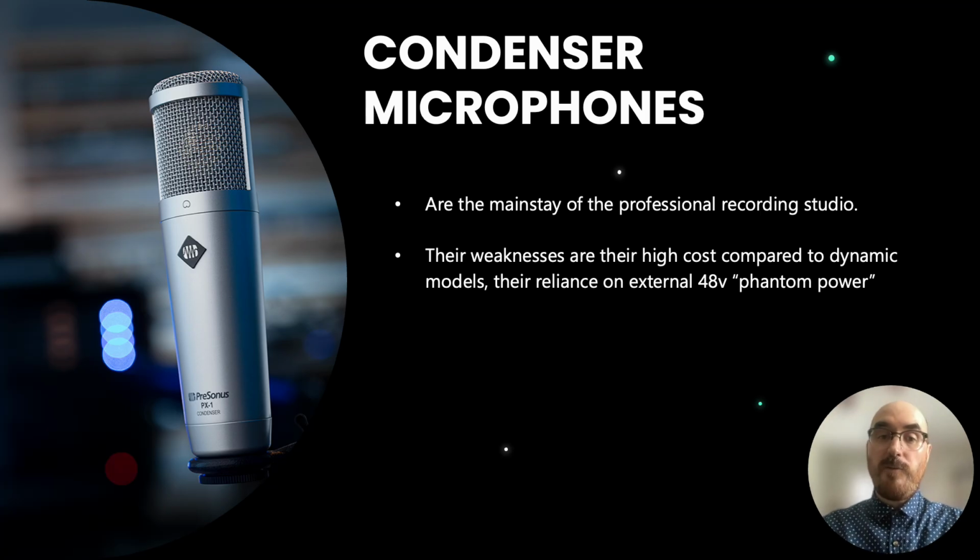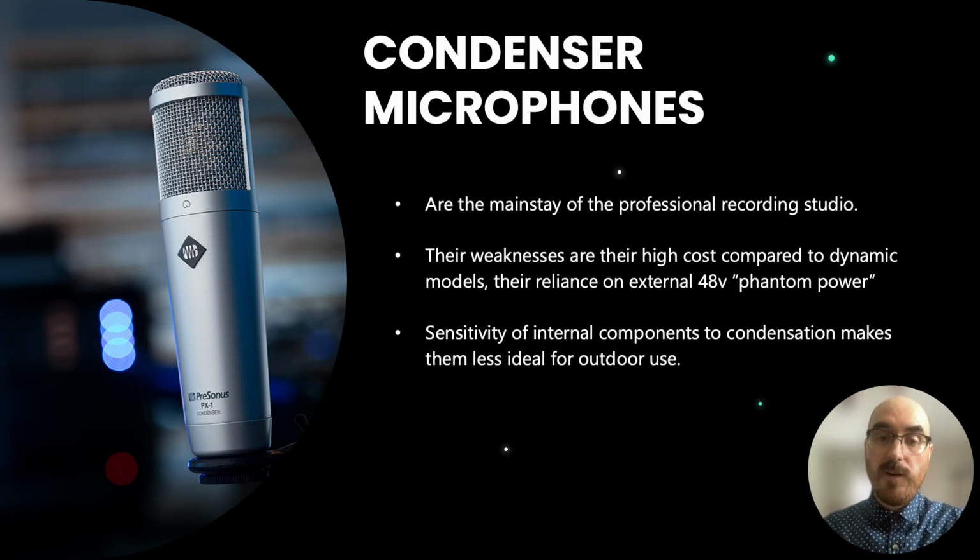So these microphones have circuitry that needs a little bit of power. So you're going to be using your microphone cable not just to pass signal from the mic to the audio interface, but you're also going to be using your cable to pass a little bit of voltage, 48 volts, to the microphone, so the internal circuitry has enough power to work. Sensitivity of internal components to condensation makes them less ideal for outdoor use.